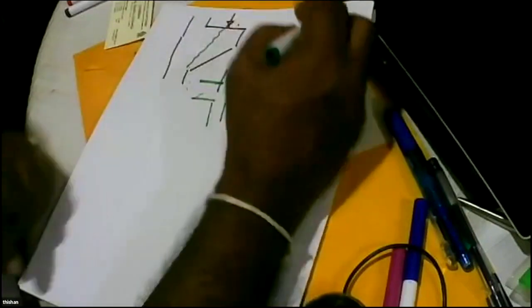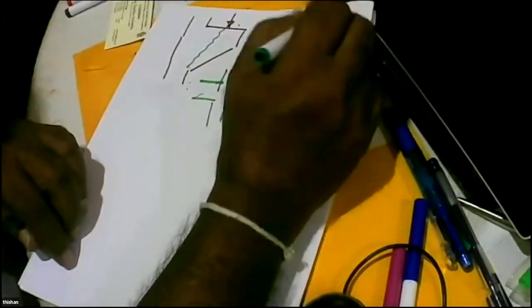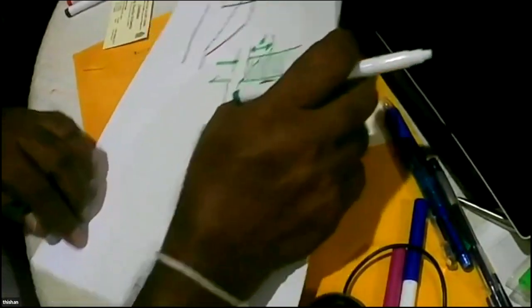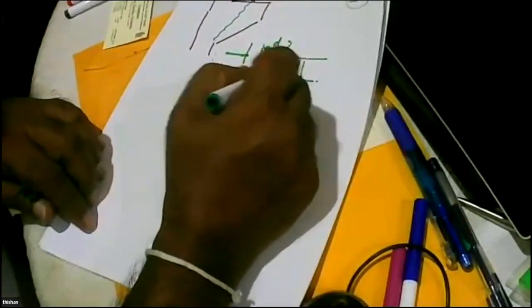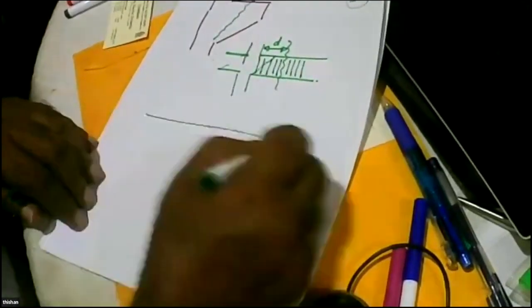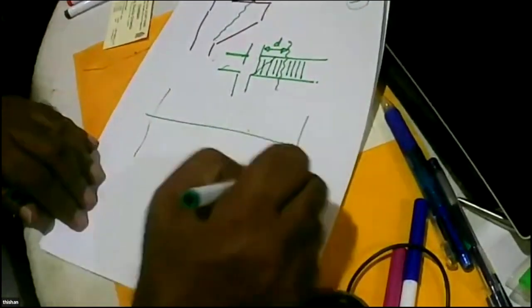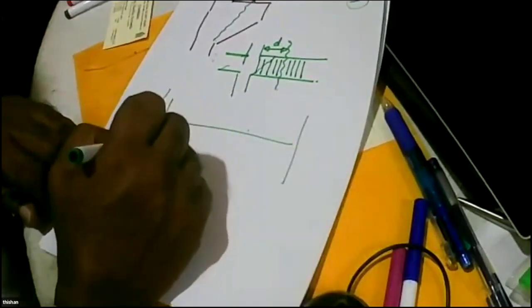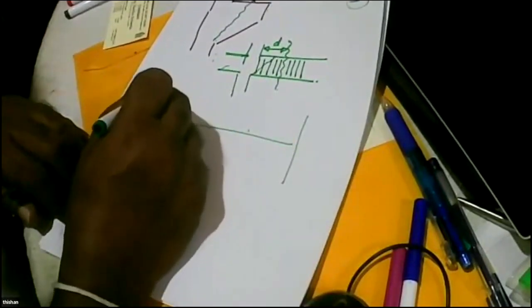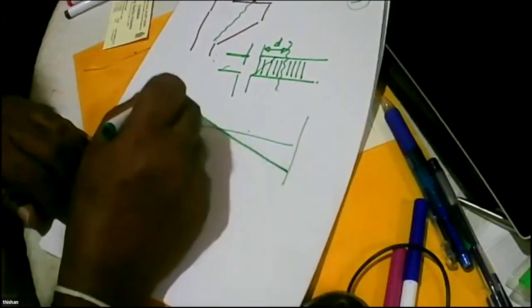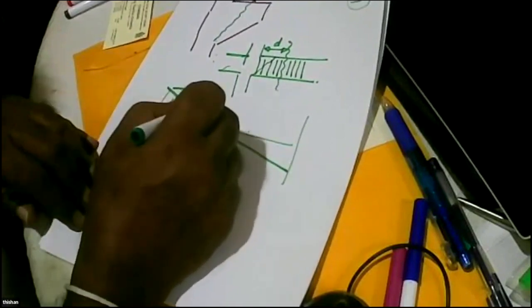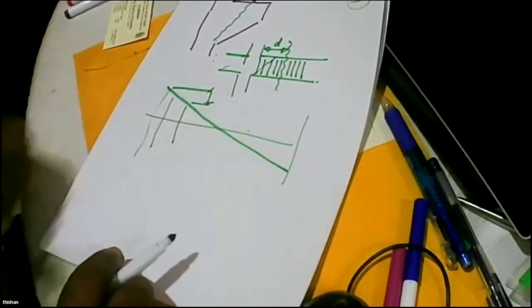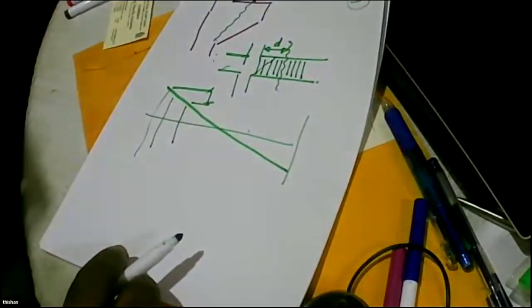So what we do is, we check at D away. And when you are checking D away, this center line, this is the face of the support, this is D away. So in this bending moment diagram, you find there's a substantial difference between these two shear forces. So why we check D away is because of this enhancement.